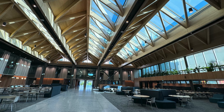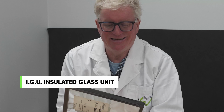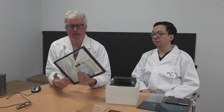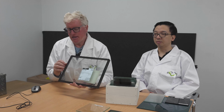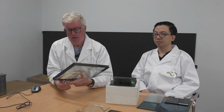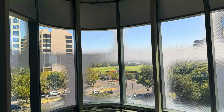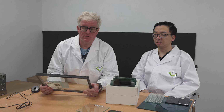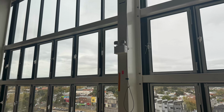I'd like to talk a little bit about what we call double IG or triple IG units. Insulated glass units is what IG stands for. Here we have a double insulated glass unit. It has a cavity in between the glass, and the cavity is what gives it some better thermal performance in terms of its conductivity or its insulation value. The 4 mil Low-E plus glass is what I'm holding here.